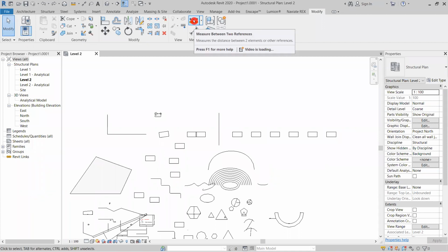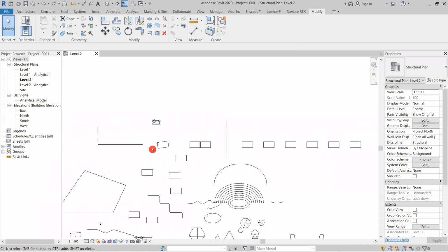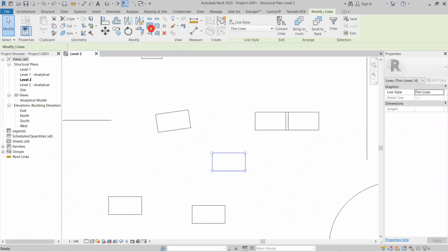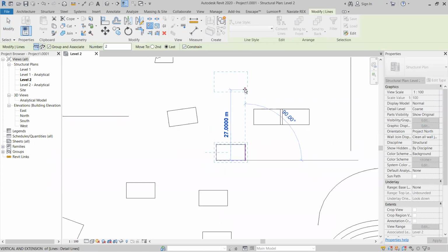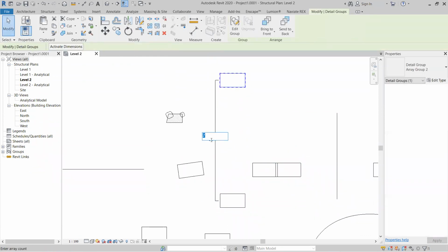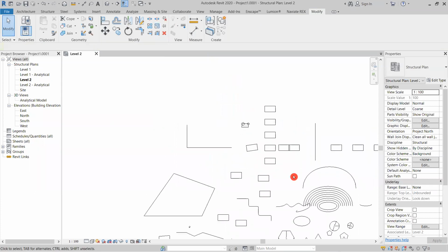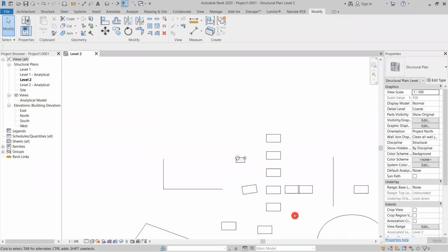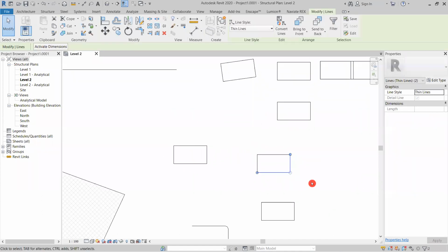Click here. Sir, how will you do it vertically? Same, brother. If you want to create a vertical, click the objects, array, first point and second point, like this, 5. Right, if you want to create any type, click here and array.